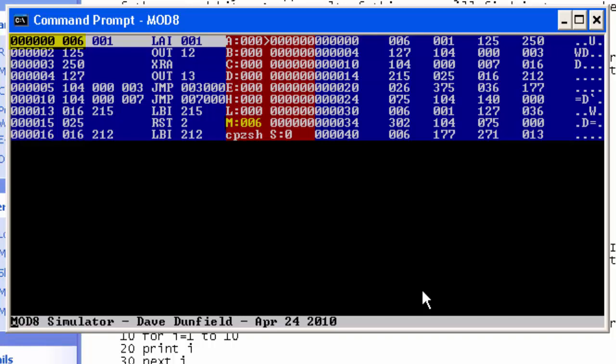And so if we were referencing that as a memory location, we would be getting the 06, and that's exactly what's there. Below that are the flags. We can see we have our carry, our parity, there's 0, and our sign. And these are lowercase, meaning that they're not set. As soon as one of these flags is set, it'll go to uppercase.